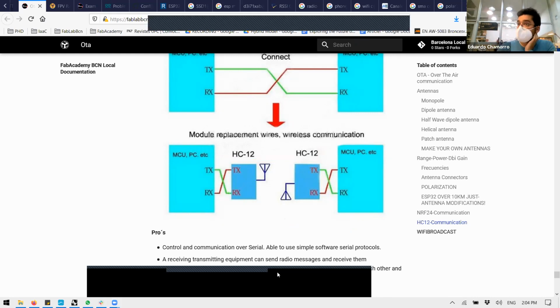3D printers right now, we have the motherboard that controls the motors, no? The screen has an SD card. The SD card, in this case, is not actually read directly by the controller. It is read by another controller that is in the LCD screen holder. And these guys actually communicate. I'm not sure right now, but I think it's I2C.